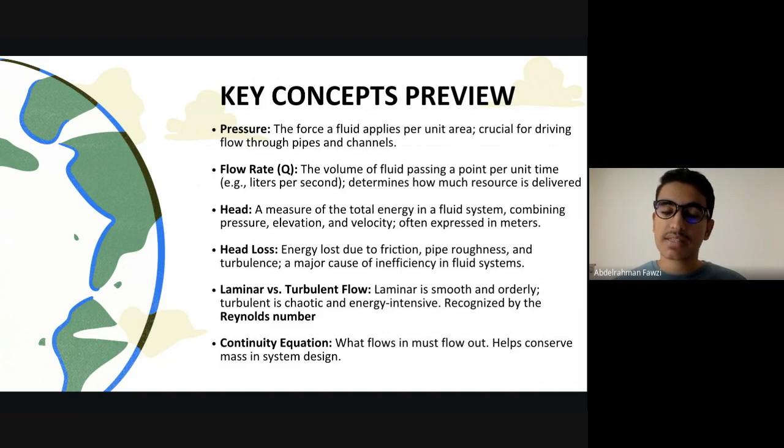Second concept is the flow rate, or we can call it the discharge. The flow rate is the volume of the fluid passing per unit time. For example, 5 liters per second. Why is it important? Because there is no fluid mechanics issue that you can solve without understanding this concept, the flow rate.